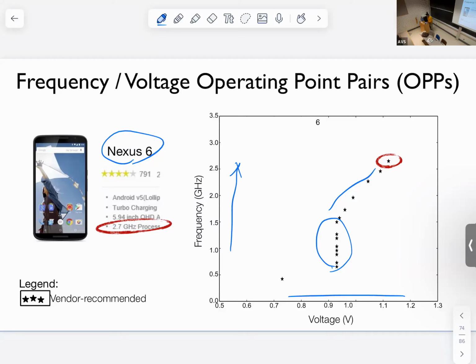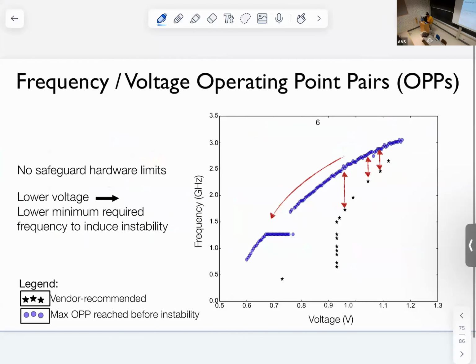Usually we have somewhere between 10 to 20 different operating points. These are predetermined tables within the voltage governors. Once you turn on your system and start using it, it moves along this direction. Going up, this corner is the fastest corner, but it's the least power efficient. This corner is the slowest corner, but the most power efficient. That's the idea of the operating points of DVFS.